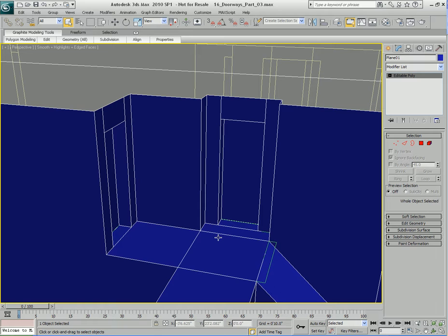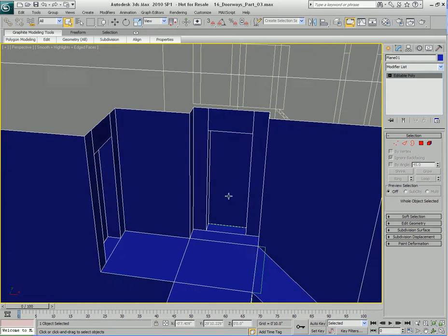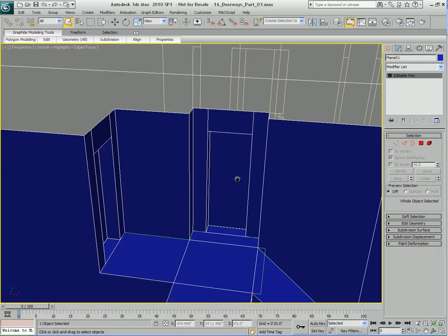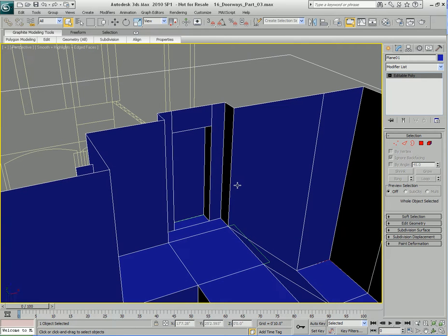So what I'm going to do in this video is we're going to see how we can use 3ds Max built-in features to create ourselves some placeholders for the doors. What do I mean by placeholders? Well, we're going to create some temporary doors that we're going to place at all of our doorways to start to give us a final look and feel of our scene. Yet we're still pretty far off from doing that. But let's go ahead and work on the doors.